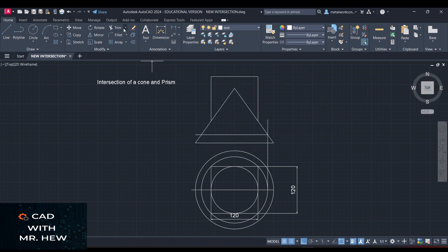All right, let me trim off the excess lines. These are construction lines. If you were using the traditional instruments such as a T-square and set-square, you would let them stay, because those lines would be drawn with a 4H pencil and they would represent construction lines. All right. So this disc will be the lowest point on the prism, right?